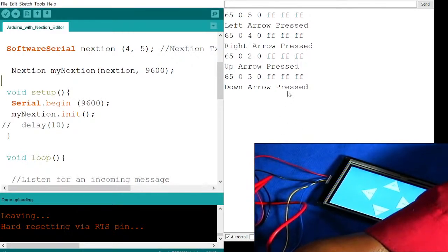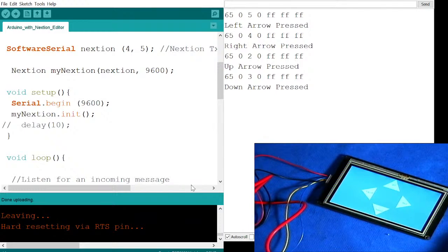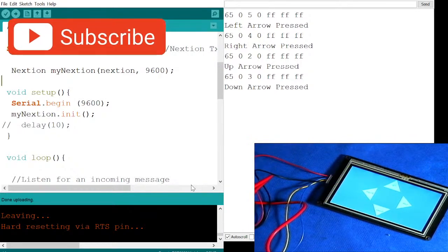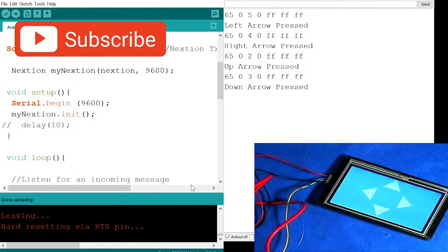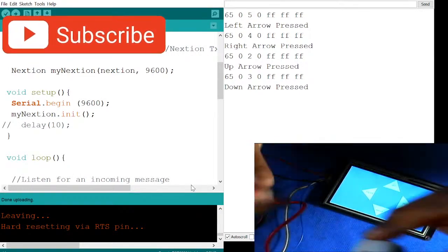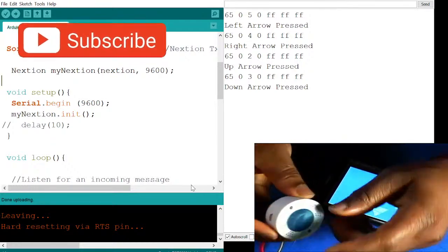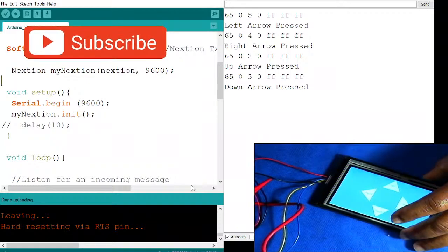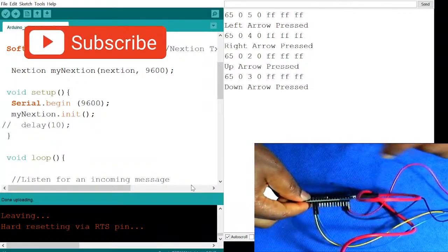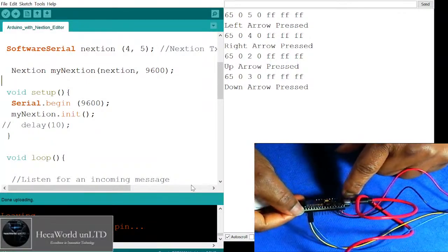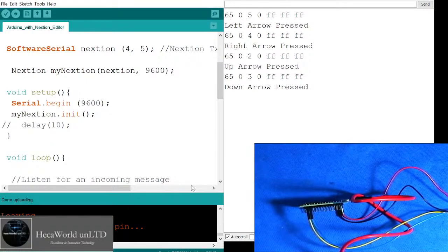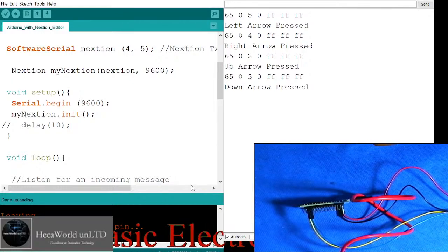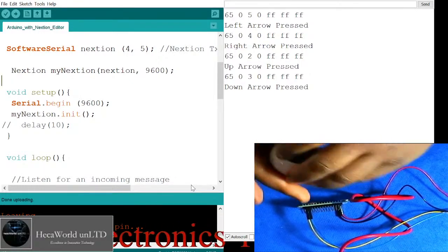And then when we fixed that, we got another error. The port was having an issue. I have to switch my ports right to left and left to right. And then my initial USB cable I was using was a power only USB cable. It was a USB cable for this camera. So it's power only. It's not for data. And when I tried to use it on the Arduino, on my ESP8266, it didn't work. Why? Because the ESP8266 needs some data, right, to read and write. But I was using a power only cable. It didn't work. I had to replace that.